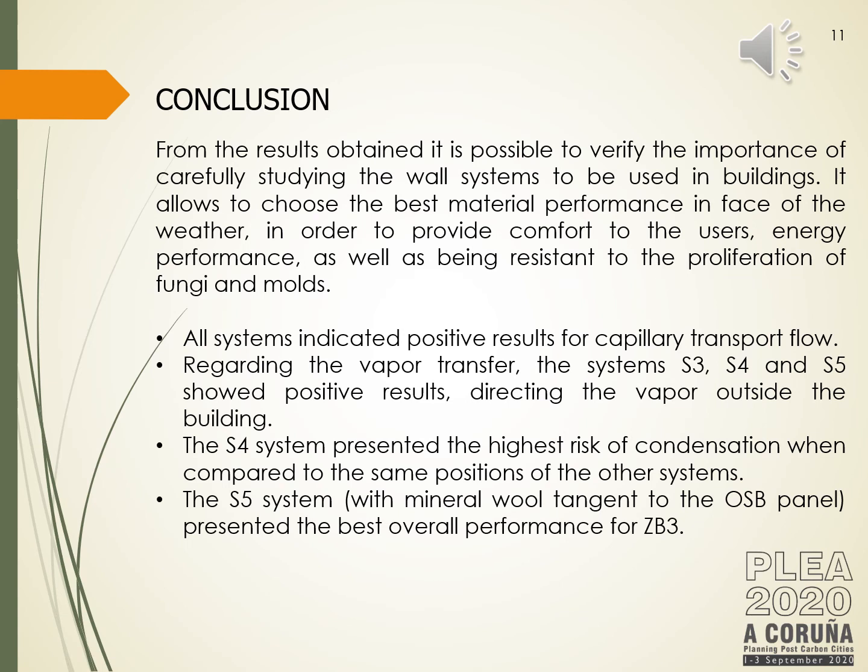As conclusion, from the results obtained, it was possible to verify the importance of carefully studying the wall system to be used in buildings. In this study, we can see that all systems indicated positive results for capillarity transport flow. And regarding the vapor transfer, the systems S3, S4, and S5 show positive results, directing the vapor outside the building. And the S4 system presented the highest risk of condensation when compared to the same position of the other systems.